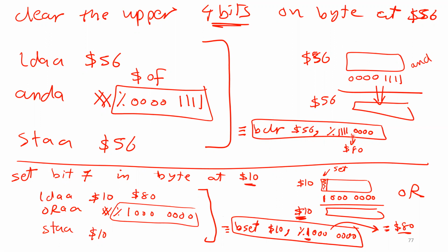In this mask, forget the AND rule where I have to put 0 because 0 and anything gives you 0. No, this is completely different. Here I'm not doing an AND operation. This is just a mask. You need to tell me which bits you want to clear. So the bits you want to clear, you have to put 1. The bits you don't want to clear, put 0. Don't be confused, please. Here is different from there. There I do an AND operation, that is why the bit I want to clear, I have to put 0, so that 0 and the bit give you 0, right? Here I'm not doing an AND operation.